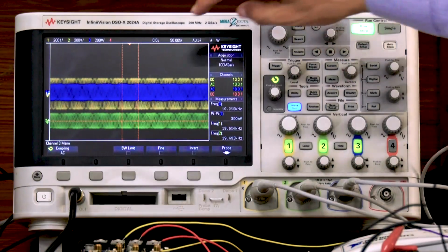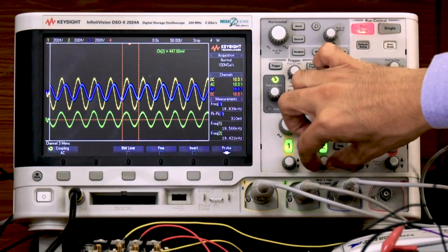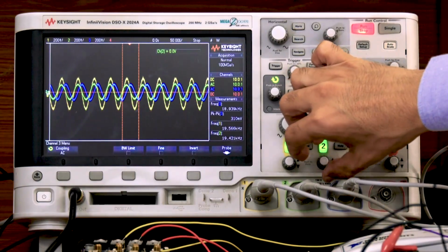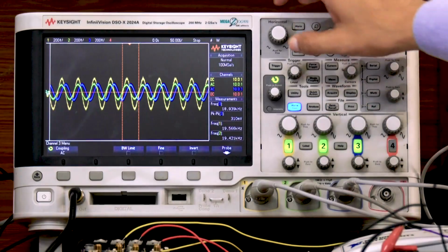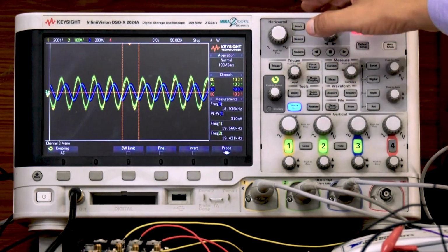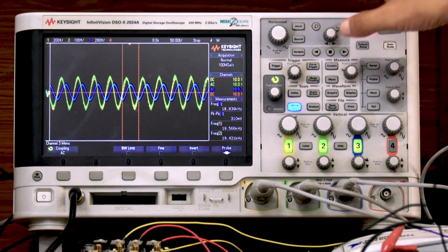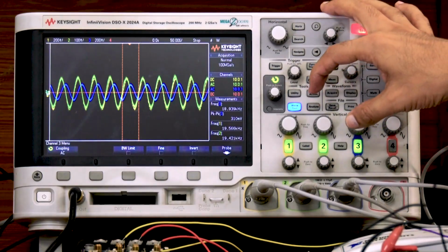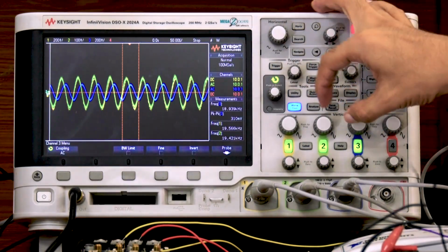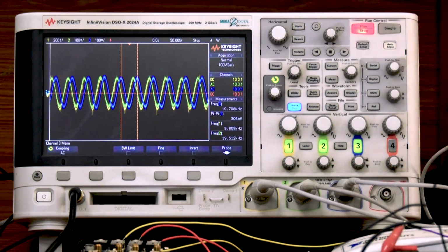So the yellow one is the input signal, and the green one is the in phase signal. So I can show you by merging these two signals. I have to increase this one. Yeah. So the green one is the in phase signal, which is almost coinciding with the input signal. The blue one is the quadrature phase, which is 90 degrees shifted. If I increase the amplitude, it can be seen that the SDFT is working properly, and it has been able to extract the in phase and quadrature of the input signal.